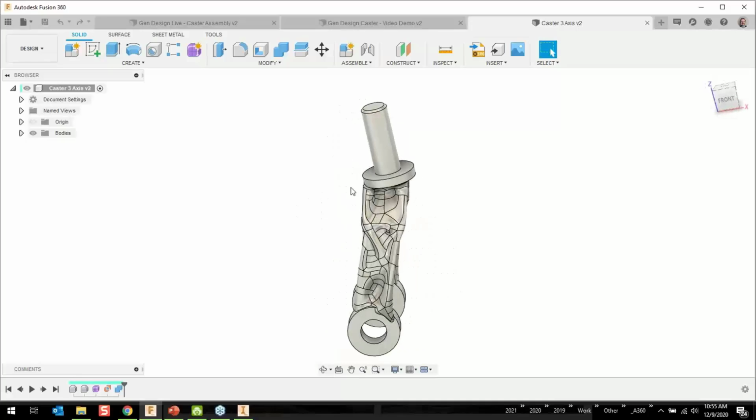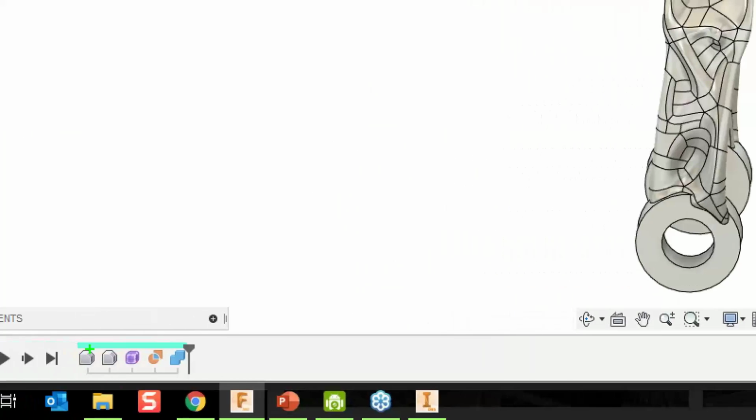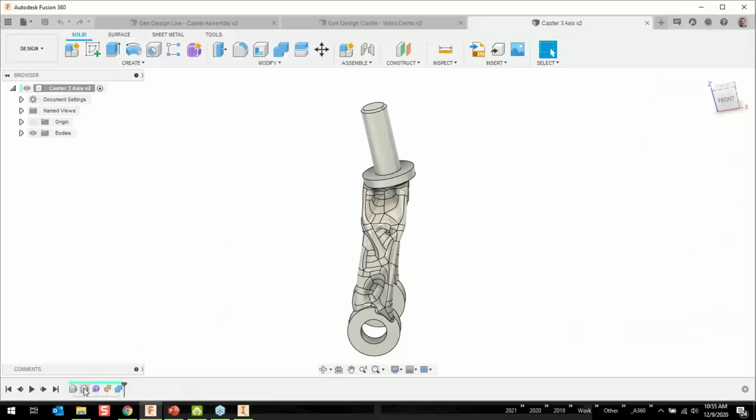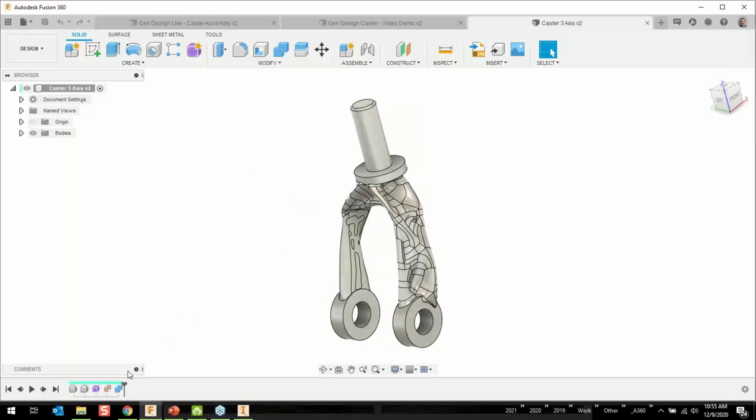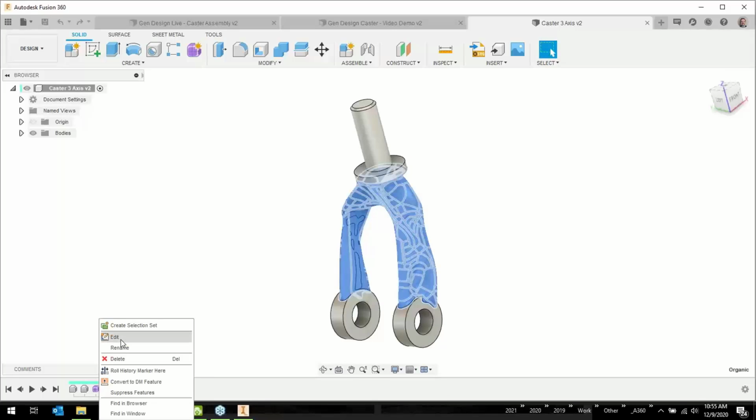So there is an actual design history down here. Basically it derives some bodies in, it creates a new one. It does this thing called boundary fill, where it combines and fills in. And then I believe it combines with that output, or it does a merge with your preserved bodies. This T-spline shape in here, I can actually modify that. If I go in here, I can say edit.